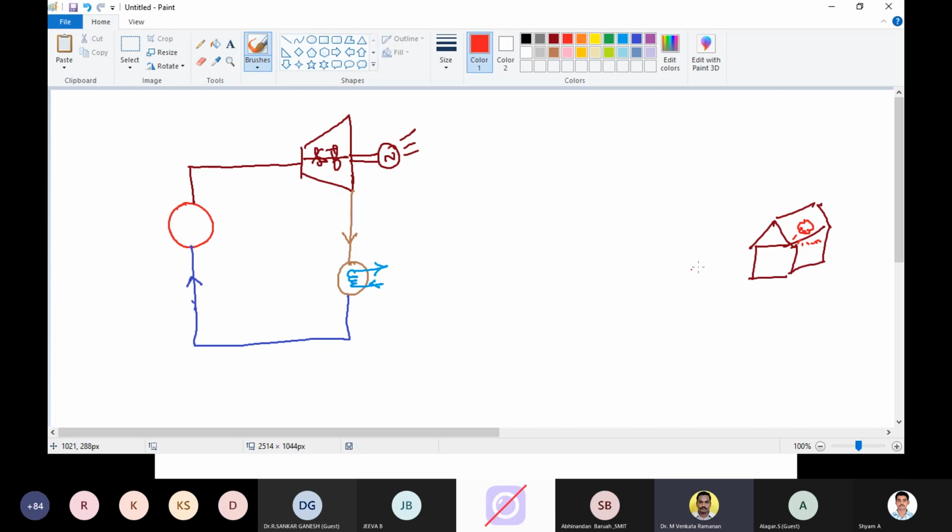The mechanism is that we have a step up transformer here. The power would be available here, and the secondary coil will have more turns. This is a step up transformer. The power gets boosted up. Voltage becomes higher and current becomes lower. As I was informing you, the intention is to make the I square R loss lower. This comes through the grid.